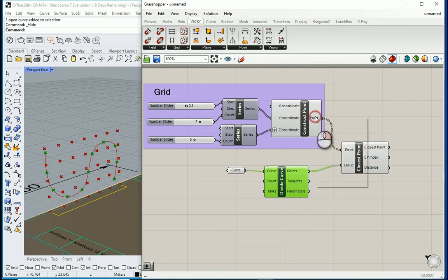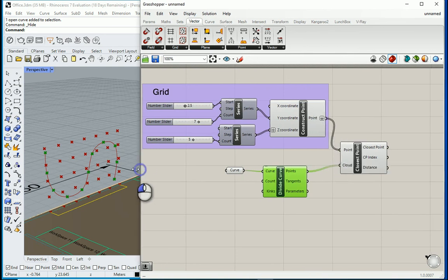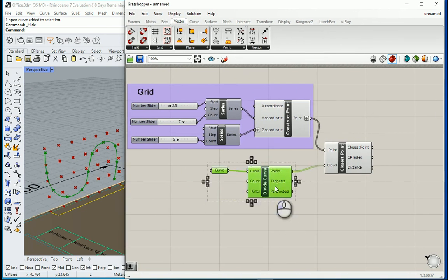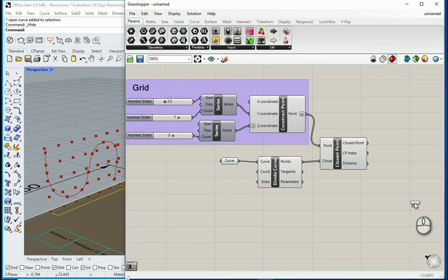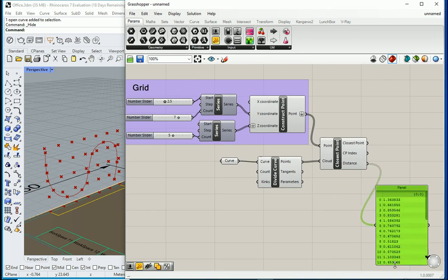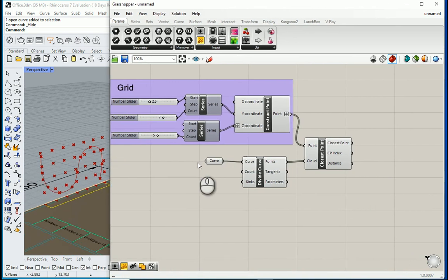And I want to actually flatten this item because you see it was a list inside a list, but I want all of them in one single list. Now, if I bring a panel, you see we have actually a set of distances here, right? So let's say if I create a polygon, relate the size of the polygon to this distance. That's what I'm going to do.